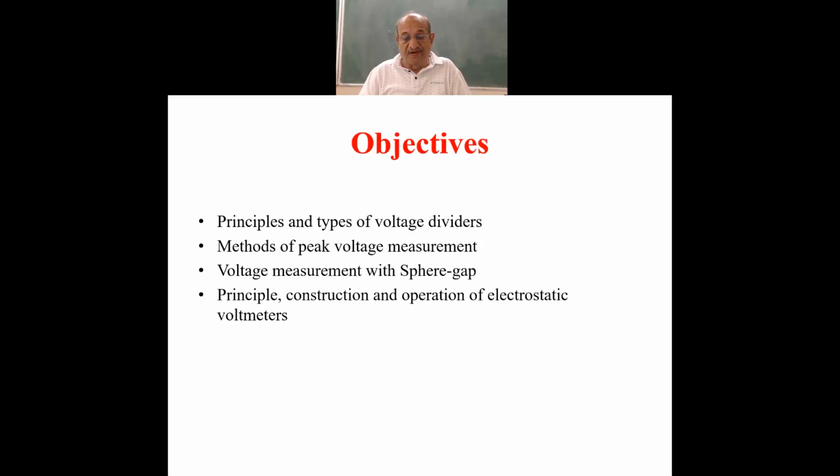In case of a capacitor, the leading power factor is there. You know that normally in the power system, the power factor is lagging. But if you have only a capacitor to be tested from a transformer, the current drawn by the test transformer will be capacitive. Let's draw it.